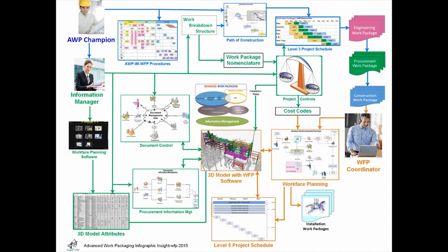As the materials are confirmed through soft allocation, the IWPs move into backlog, which is then used to develop the 3-week look-ahead. The sequence of activities in the schedule are then linked to IWPs in the 3D model and played out as a 4D simulation of construction.